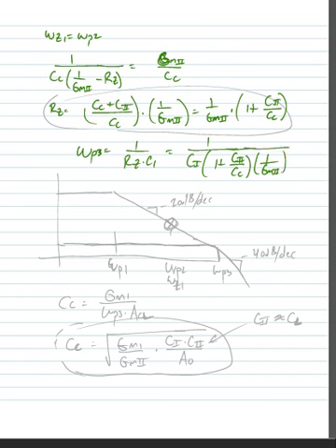What we're doing now is we'd like to have a 45-degree phase margin. And what we're seeing here is what we've done with our compensation capacitance and zero. We have our first pole, omega p1, when we're drawing our Bode plot.